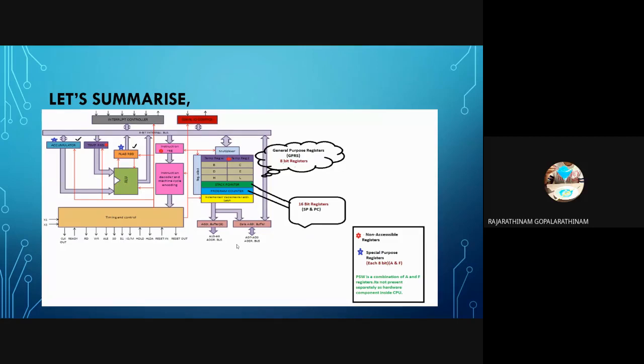So I have a 3-byte instruction, LXI B, 2000, right? How many bytes is the instruction? 3 bytes. First byte is the opcode, which is 11. It is going to occupy an 8-bit memory location, which is also going to have an address. The opcode is going to have an address in the memory. Then the other 2 bytes are 00 and 20.